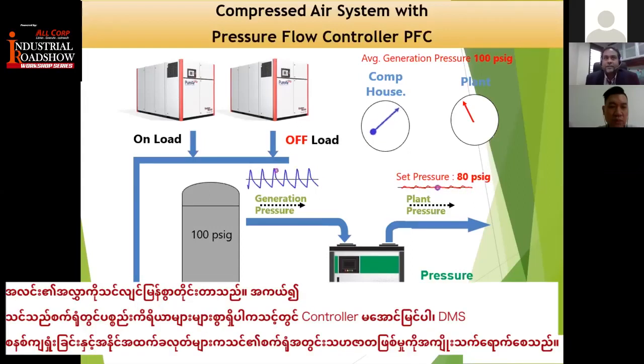And the other thing is, if you have a lot of electronic equipment in the plant that keeps failing, like a controller failing, BMS system failing, and tripping of your breakers, right? This is all caused by a high harmonics level in the plant.